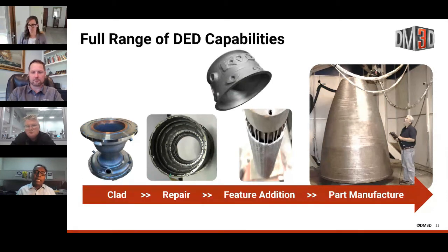The reason being, unlike powder bed fusion where you need a horizontal layer of powder to scan, here you could deposit on 3D surfaces, freestanding 3D surfaces. So let's say after finishing, you find a defect 2 feet below the top. You can simply go back there, grind out the defect with manual tools, and then program that in, and then go and repair that damaged area. So that's a unique aspect of DED.